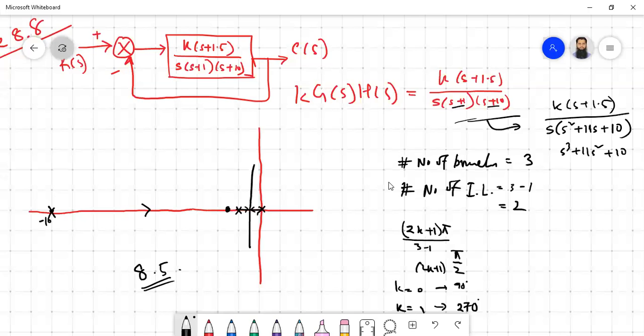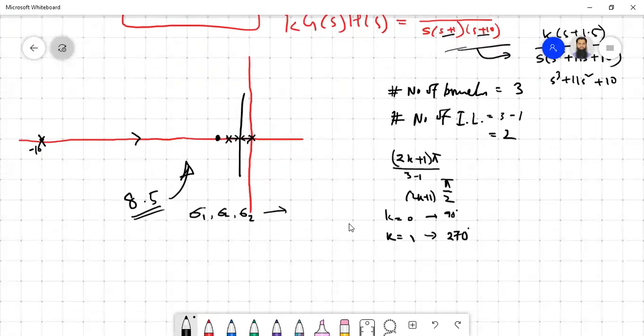It is essential in cases like this, where you can find the three sigma values, sigma 1, sigma 2, sigma 3, for the real axis breakaway and break-in points. You can see that one of them is here and another point is here, so they go this way. Another breakaway point you will find somewhere here. One of them goes in that direction, the other in that direction. So they come, and then you have that line going up and down.